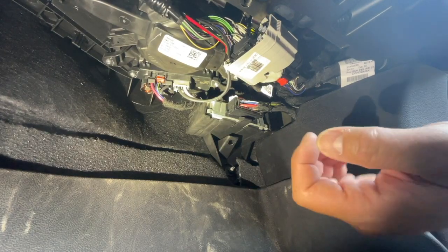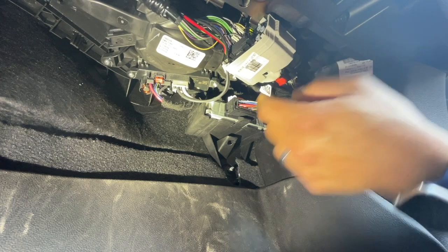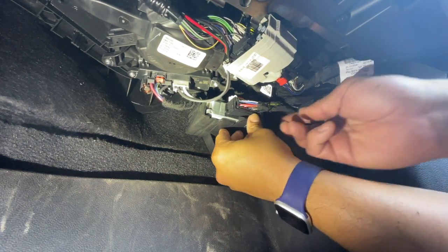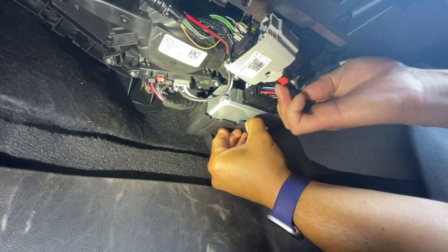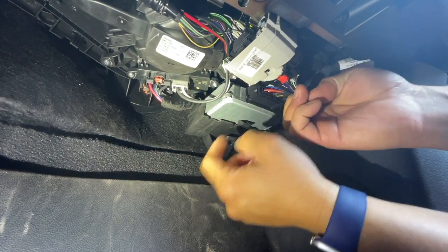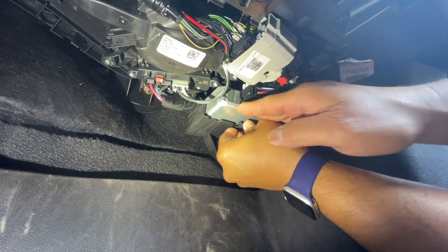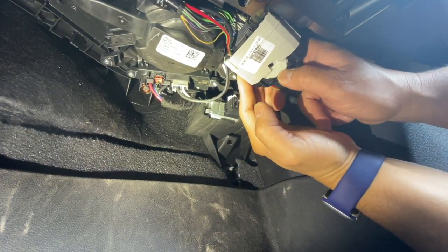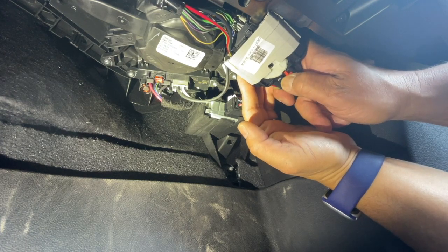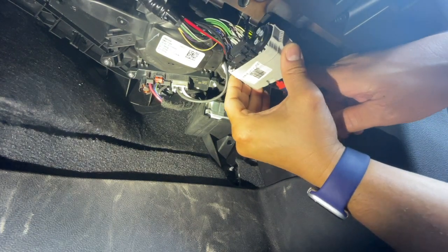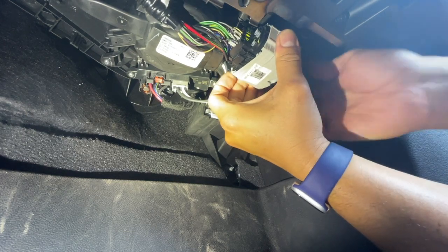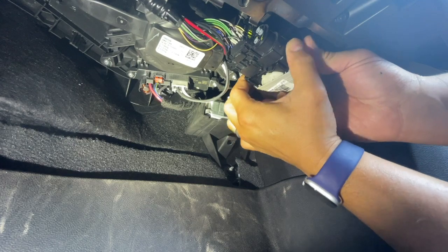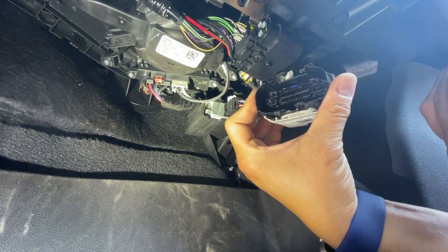Okay, so underneath here, we're going to be looking at this connector. Now, the instructions specify to unplug the inverter module first, but if I try to remove this module, this connector gets in the way. So I'm going to go and disconnect this module first. So this module here has a red CPA. You want to pull this away from the connector, so you're going to move it down, and that allows you to move this gray lock here. So this gray lock is going to move to the right, and you want to slide it all the way back, and then it will release from the connector.